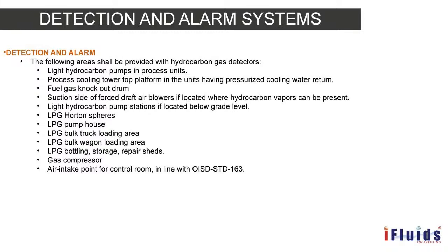What are the areas which require hydrocarbon detection systems, or otherwise flame detection systems? There is no such criteria with respect to the flame detection system, whereas with respect to the hydrocarbon system as well as the smoke and heat detection system, some criteria are mentioned. The major critical areas mentioned here which require hydrocarbon detectors are, if you handle a light hydrocarbon pump, then you mandatorily need to provide this hydrocarbon protection system.